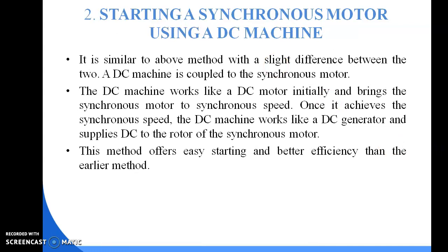Now, coming to the second method of starting: starting a synchronous motor using a DC machine. It is similar to the above method, that is using induction motor, with a slight difference in the two. A DC machine is coupled to the synchronous motor.